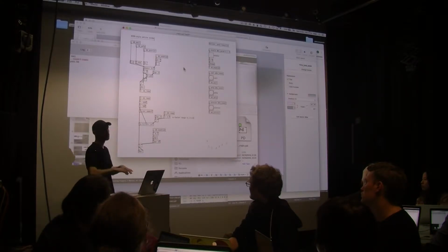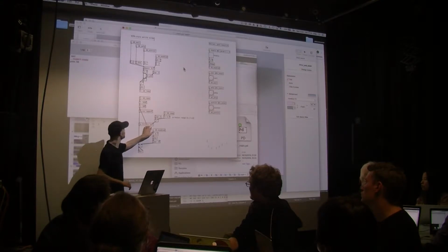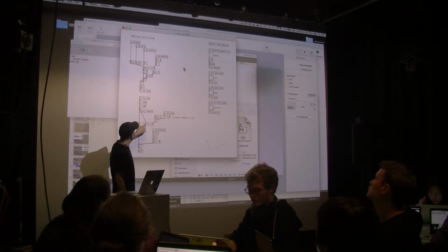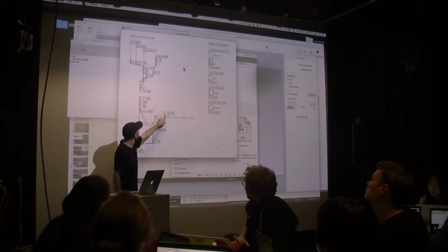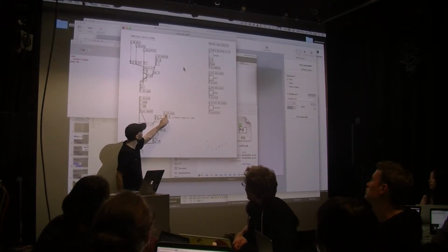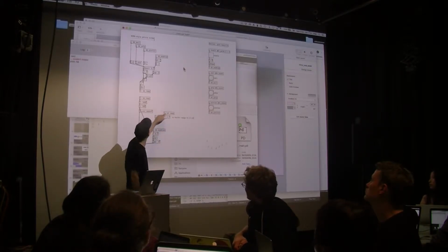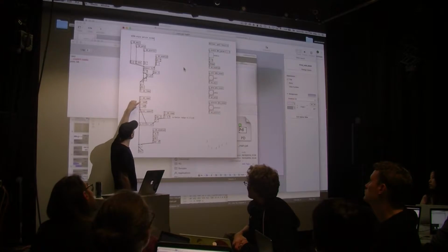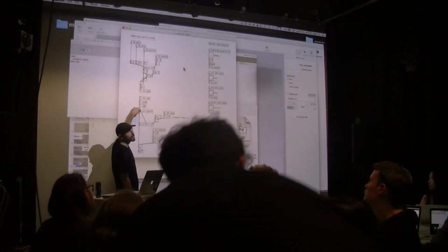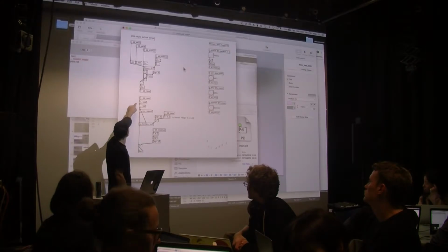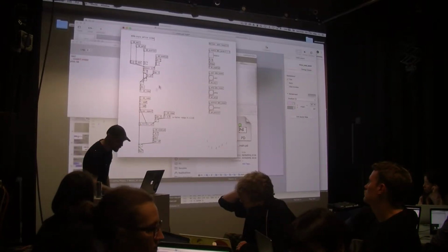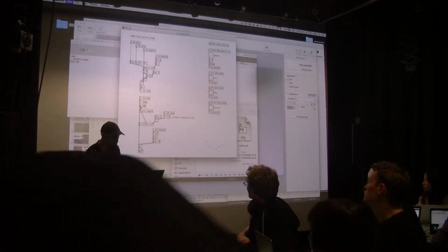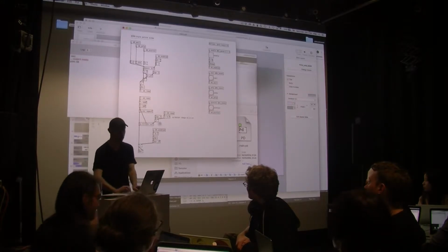If all that means nothing to you, don't worry too much. Basically, it's a bandpass filter. And we are changing the Q factor over here based on this ramp signal. So we've discovered there's this ramp object. Where does that ramp come from? It comes from here, okay? And if we look here, we see we're using the same ramp signal over here as well to control the frequency of the square wave oscillator, okay? So basically, the signal guts of this model are over here, square wave through a filter. We're changing the frequency and we're changing the cutoff and resonance of the filter as well.